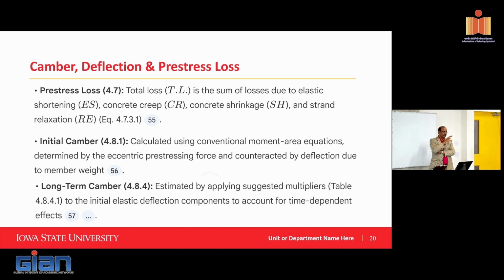The losses are different in each state. You don't have to account for the losses that are going to happen 20 years later when you do the precast erection. But you have a high amount of prestress at that time. So those are the important pieces to pay attention to so that you get the right prestress to go with the right limit state when you calculate the actual losses and the corresponding stresses.